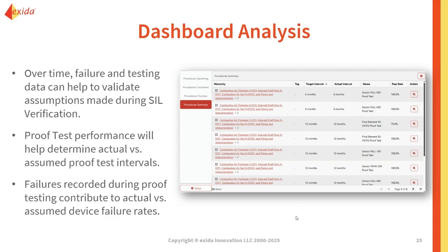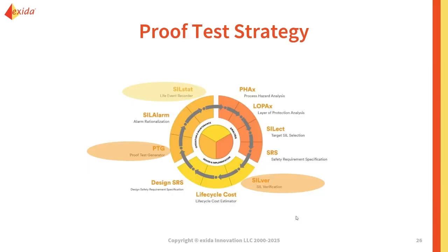If you're just looking to view your data at a glance in context, you would use the dashboard for that. And ultimately, you want to take that data to approach your revalidation. So say when you do your SIL verification revalidation every 5 years, you would be able to now approach that with this data in hand and input the parameters such that you know how often you're doing your proof testing, you know how fast you can do a repair, you know when you're ultimately changing out or repairing your equipment at the end of the mission time.